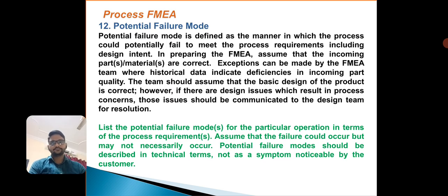List the potential failure modes for the particular operation in terms of the process requirement. Assume that the failure could occur but may not necessarily occur. Potential failure mode should be described in technical terms, not as symptoms noticed by the customer.